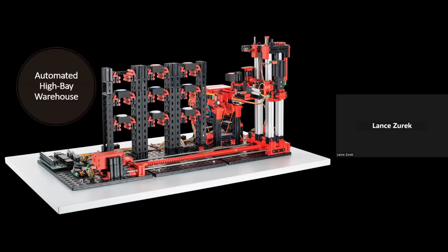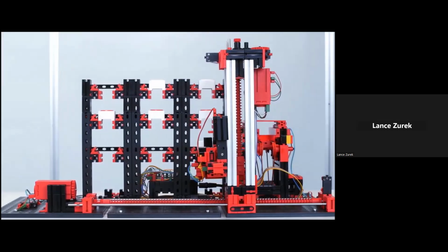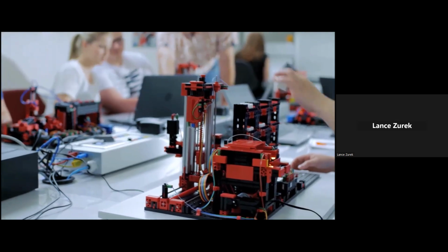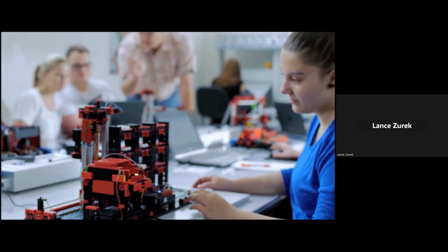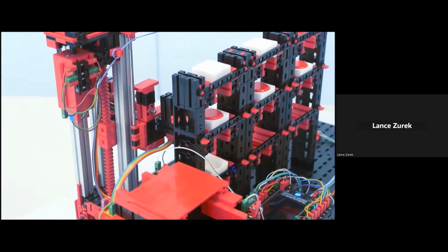Next up, we are going to look at the high bay automated warehouse. This model features a transfer station with a conveyor belt, along with a shelf stacking mechanism for storing and retrieving workpiece carrier trays in 9 individual storage spots. Components of this model include 2 encoder motors, 2 mini motors, 4 push-button limit switches, 2 photo transistors, 2 LED light barriers, and a selection of different colored workpieces, along with carrier trays for each.